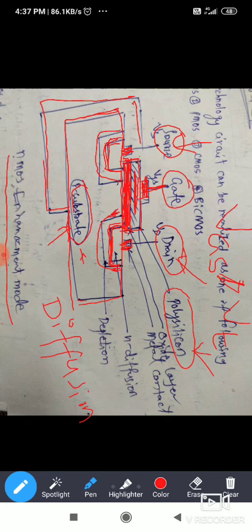VGS means we will apply some voltage, gate to source terminal. This is gate, this is source. We will apply gate to source voltage, and here the p type holes are the majority carriers, and the gate to source voltage you will always apply as negative voltage.